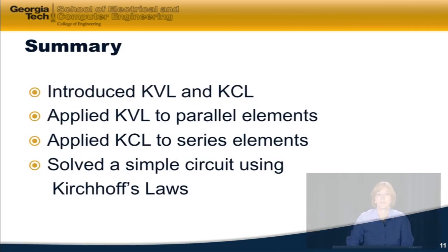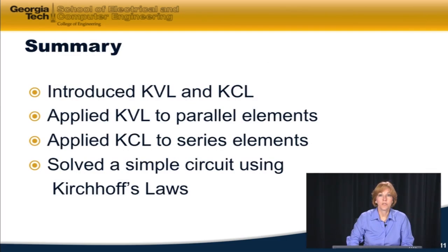So in summary, we've introduced the KVL and KCL, applied the KVL to parallel elements and series elements, and solved simple circuits using Kirchhoff's laws. All of this is applied to circuits with impedances. The bottom line is an impedance acts like a complex resistance. All of our standard laws apply. The only thing is it's messier because it's complex numbers.